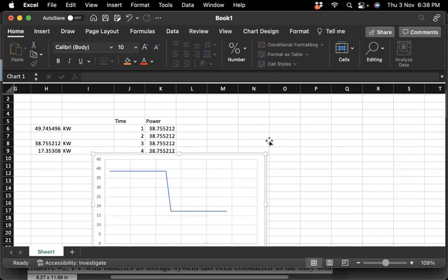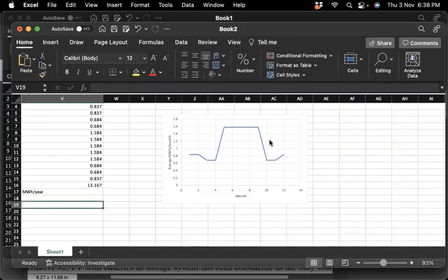So loads can differ in terms of the level of criticality, to what extent this load is critical, and also in terms of their seasonal consumption. Is it a seasonal load like air conditioning and lighting, or is it a flat load or a uniform load like the case of office buildings and all this? And accordingly, you can have different sizing profiles or different load profiles.